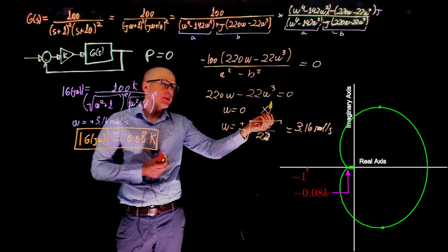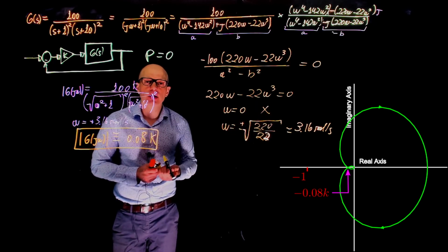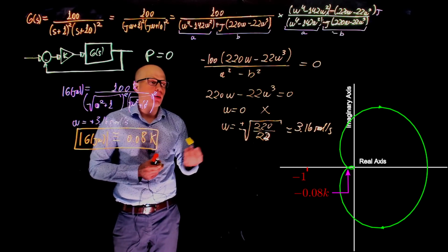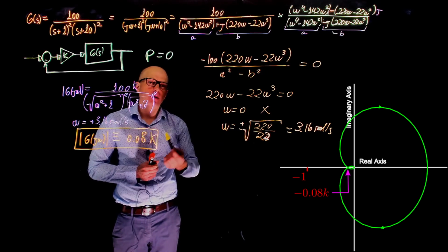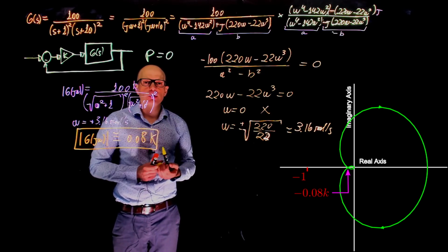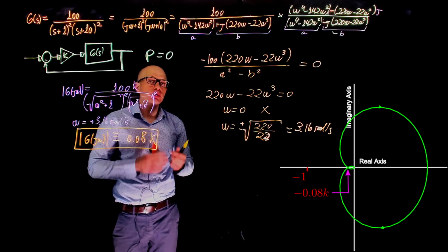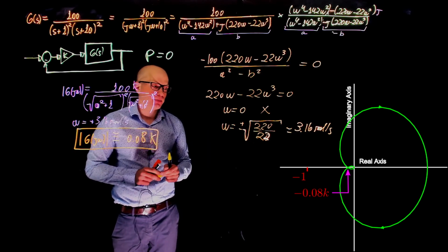However, if that point is exactly at -1, then the system becomes marginally stable. And if we are now to the left of -1, then the system becomes closed loop unstable with two encirclements of -1, Z equals 2, two unstable closed loop poles.